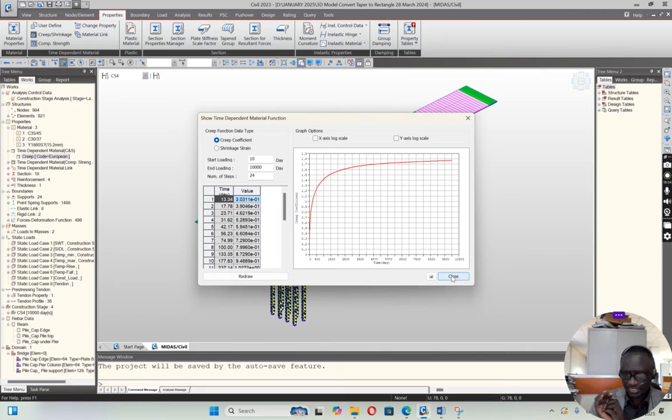I told you the other day that when you are pre-stressing, you are trying to keep the concrete section in compression, and you try to limit cracks. But if this compressive force gives you strength higher than the capacity of the member, then it will crush. So that's why the minimum grade for pre-stressing starts at about, I think, 40 MPa compressive, which is about 32 characteristic grade, going to 40, 50, 60, like that.